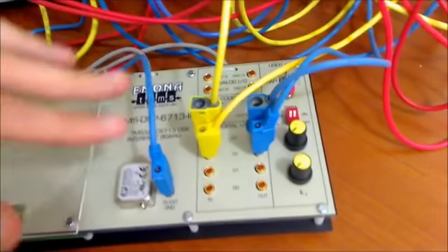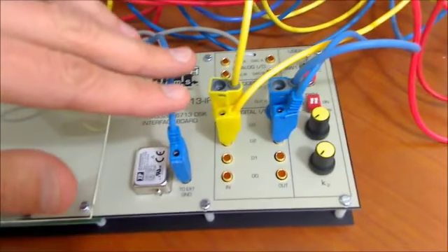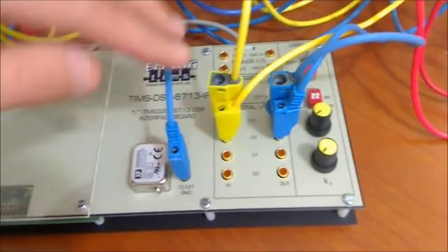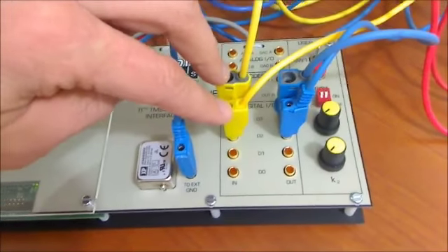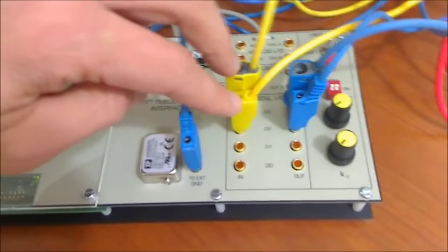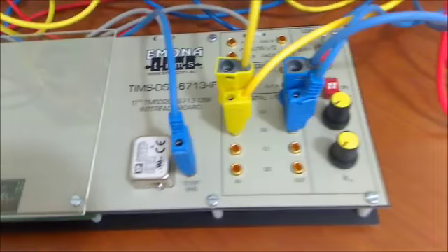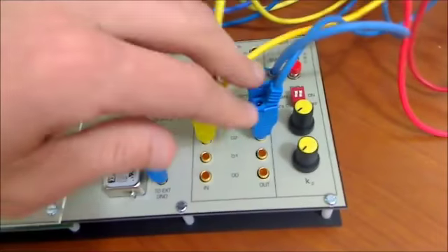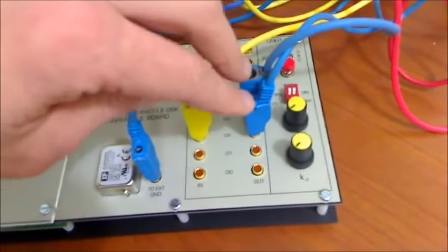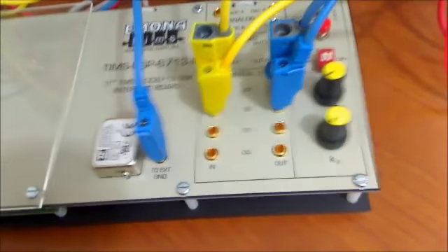So we've taken the signal out of the line code decoder, which is basically our recovered TTL signal. We input it into the digital inputs, and then we're running the program on the laptop, and the output is the deconvolved signals, which we'll have a look at in a minute. We're switching over to the laptop.